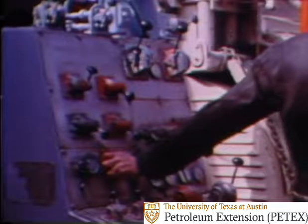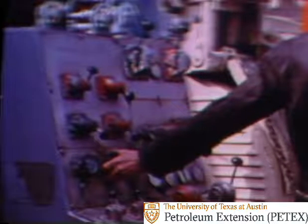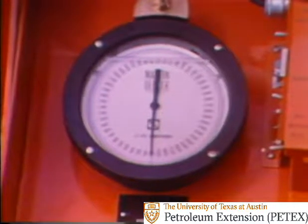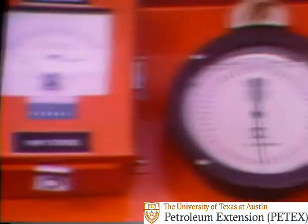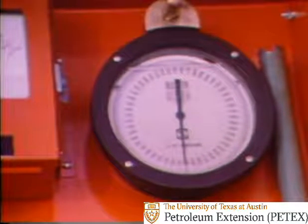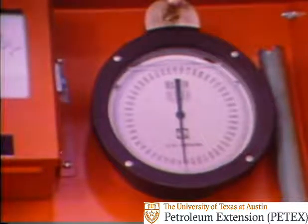Pumping can then be stopped, and well pressure should be 0 on the drill pipe and casing. If it's not, the mud weight required to kill the well must be recalculated using the observed drill pipe shut-in pressure. The mud weight is increased, and a second operation repeated.